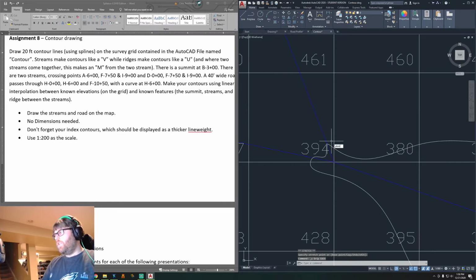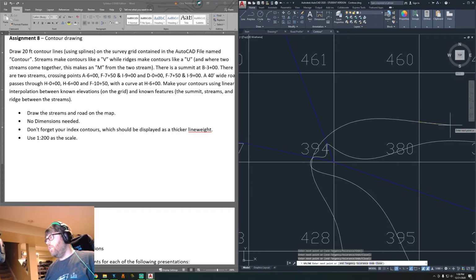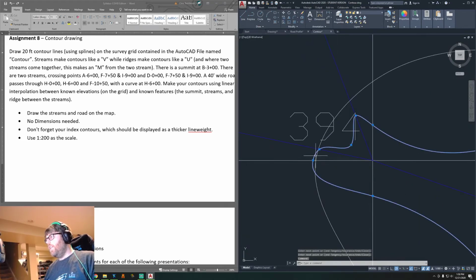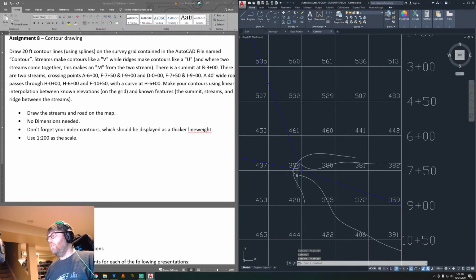And if there was, say, another spline, nope, that's not how you spell spline. If there was another spline, say a 420, that went from here to here to here, and you had it do something like this, and it went off that way, these lines can't cross each other. So that's bad as well. You've got to make sure after you manipulate this to get your shape that it doesn't end up crossing a line that it shouldn't. Say this is a 400 line, but it crossed this 437 area. It's all bad.